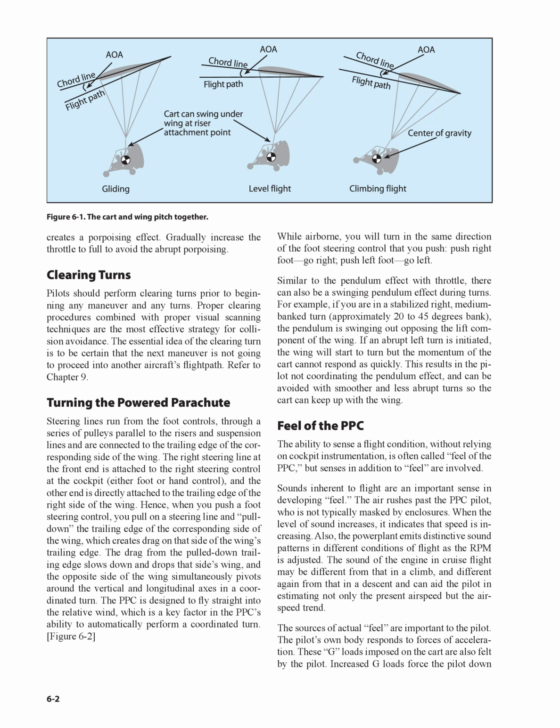Clearing turns. Pilots should perform clearing turns prior to beginning any maneuver and any turns. Proper clearing procedures combined with proper visual scanning techniques are the most effective strategy for collision avoidance. The essential idea of the clearing turn is to be certain that the next maneuver is not going to proceed into another aircraft's flight path. Refer to Chapter 9. Turning.